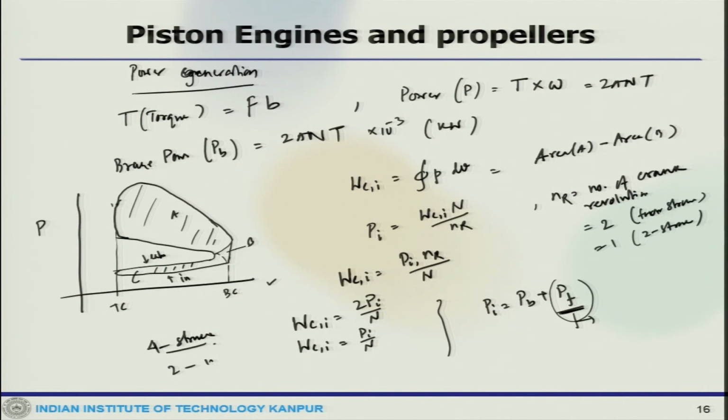And then the mechanical efficiency, eta, would be the ratio of brake power to indicated power. Typically, this is around 90% for modern automotive engines, where the revolution is around 1800 to 2400 RPM, or 75% for the maximum speed limit.